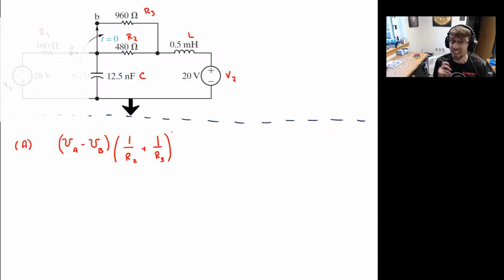And now here's the next point. I'll highlight this for node voltage, but you have the same issue for mesh current. Remember that the underlying physical idea for the node voltage method was applying KCL. You're thinking about the currents exiting that essential node, and then you write those currents in terms of potentials using Ohm's law.